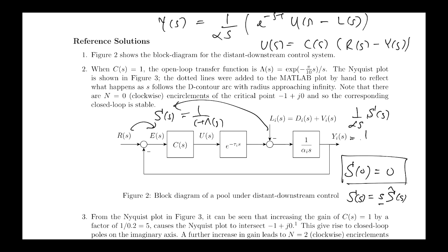It must have a factor like that you can pull out the front. And so when I put that in here, that goes with that, all right? And we don't have the property that when we multiply this by the load signal, the Laplace transform, which will be 1 on s, we can't cancel the 1 on s, because it's already been cancelled by the fact that we have to include the plant transfer function when looking at the transfer function from here to here.